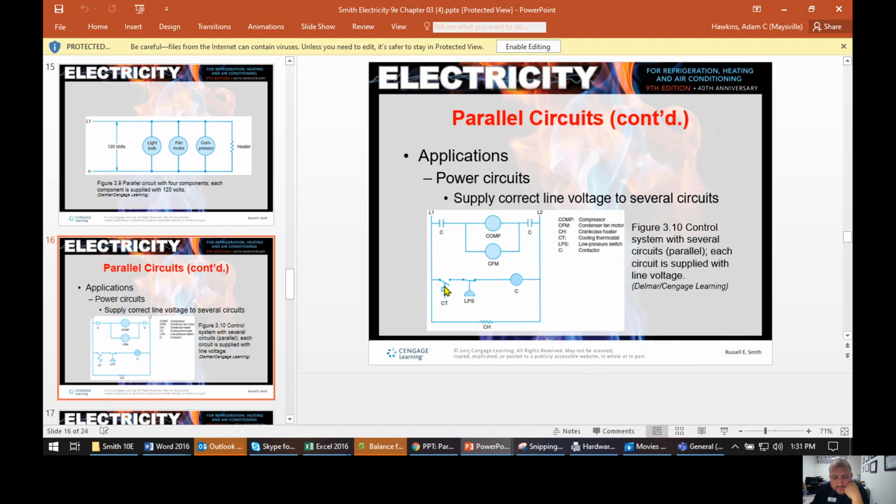And because it's drawn open, it's able to operate. It could be open or closed. And as it heats up, if you can imagine that little switch rising until it meets the other side and makes that switch. And then as it gets colder and it gets cold enough where it wants to kick off, it will be dropping back down to open that circuit up and kick itself off.